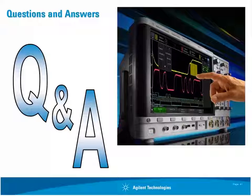So how can we put 1 million waveforms in a second if the scope's refresh is only 17 milliseconds? Well, our scopes actually have a minimum persistence, and that is the refresh rate of the scope. So for each refresh of the scope's display every 17 milliseconds, there can be thousands of waveforms on screen.